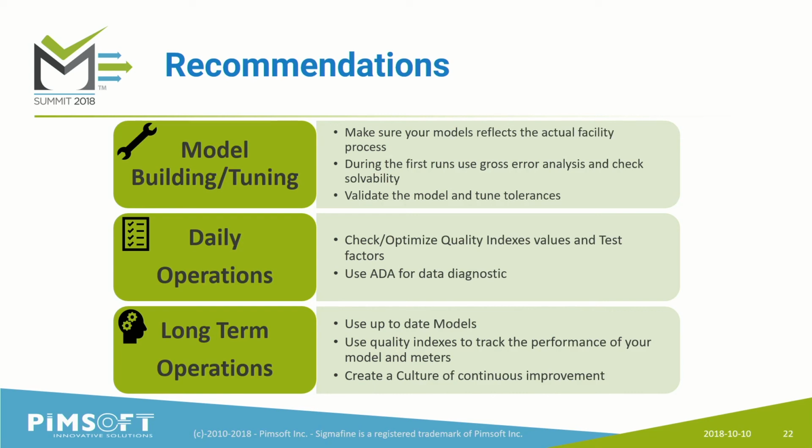If your process changes and you add a unit or something new happens in your process, you have to update your model so that it reflects exactly your process. Also in the long term, you can track the performance of your meters and see, as we saw before, if any meter or any unit is going too far in the imbalance and in the reconciliation.